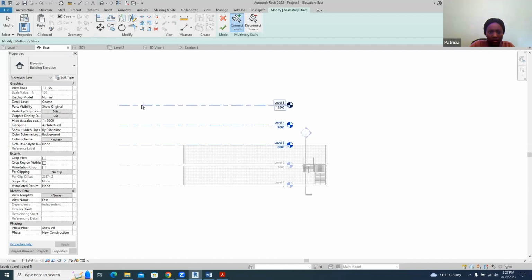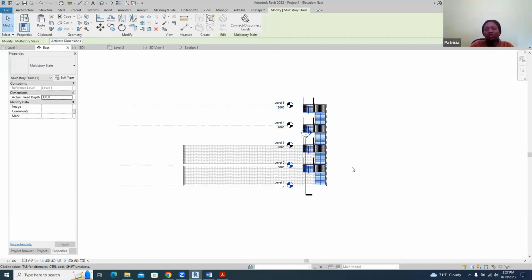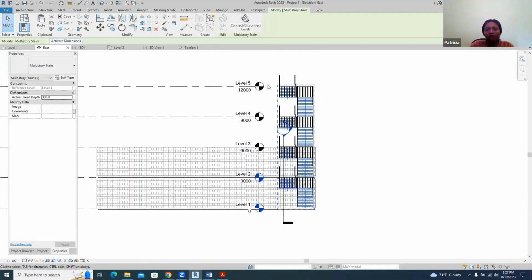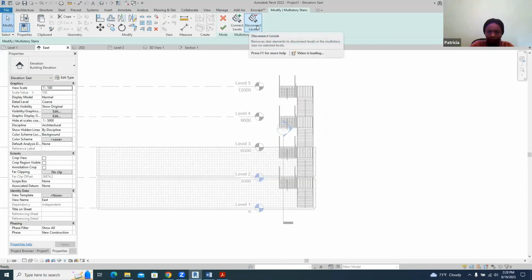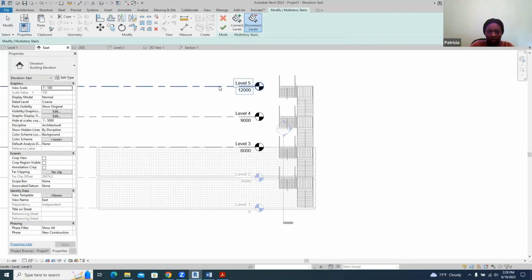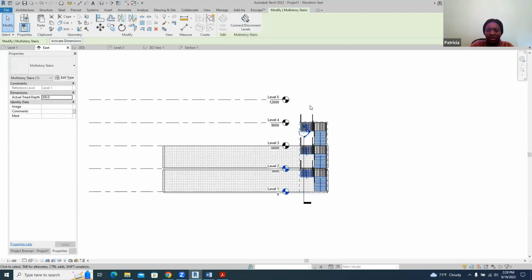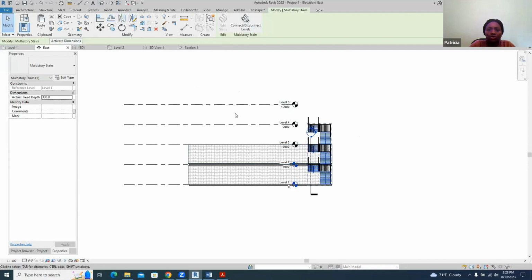control add it and this, and then I will check the mark. So we see that the stairs will repeat for all the levels that we have added. So we can go back to it and then say minus, and I click on this and check it. It removes the stairs that's connecting to that level. So with this, we are done with the stairs tutorial.